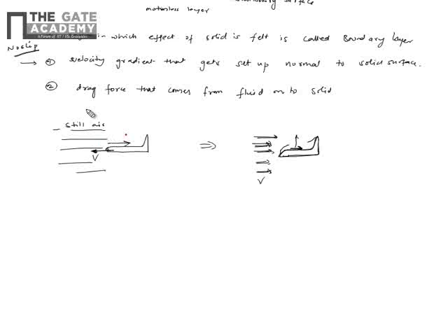The other way of saying it is, when the aeroplane is moving like this, the drag force is this way, because in still air, when the aeroplane moves, the surface tries to move left relative to the air. The air applies a fluid friction or resistance force due to viscosity, and summing up all those for the entire surface, you get a force called drag force. You need to know the drag force, because it is the force against which you need to work. So all your engine requirements, everything, will depend on your drag force.